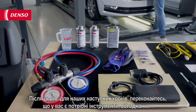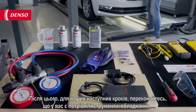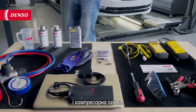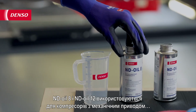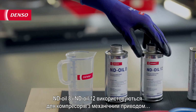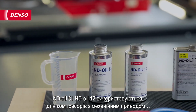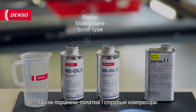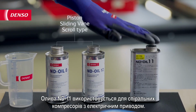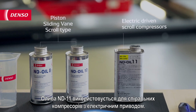Then, for our next steps, make sure you have the right tools, equipment, and compressor oil ready. There are 3 DENSO oil types available. ND Oil 8 and ND Oil 12 are used for mechanical-driven compressors, such as piston, sliding vane, and scroll type. The ND Oil 11 is used for electric-driven scroll compressors.